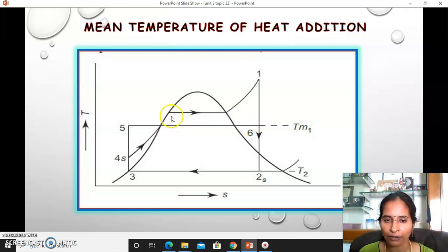According to that, you can fix your superheated temperature at the inlet and the pump and economizer inlet temperature, everything could be changed to improve not only the efficiency of the plant, but also the lifetime of the various components, especially turbine components.